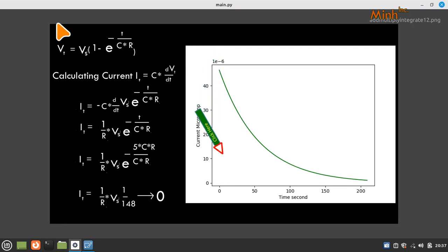It starts from 0, and then around 210 it reaches a kind of stagnant value. So we can say that 210 is the time when it becomes 0. That time is nothing but 5 into the time constant. If I see this equation closely, if I keep growing the t, if it becomes 5 into R into C, then it is almost 0. So that is called the time constant. It helps in finding the value of the capacitance.